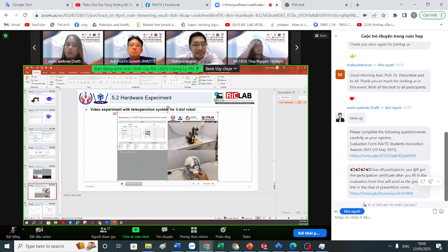Why do I control slowly, not rapidly? Because the 3D robot I designed does not work rapidly, because the step motor does not work rapidly. I generate points to control. It has many points and a delay time to generate points. That is the reason I cannot control it rapidly. I will make it rapid when I replace the step motor with another motor, an AC motor controlled by an AC driver. It is more rapid than a step motor.